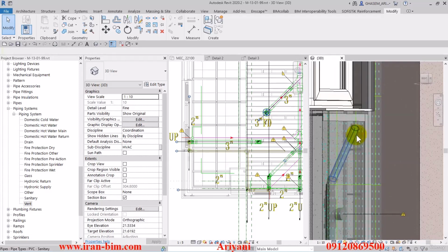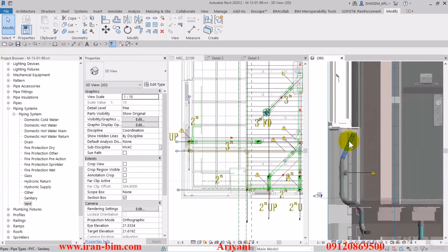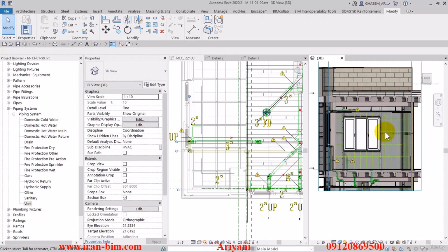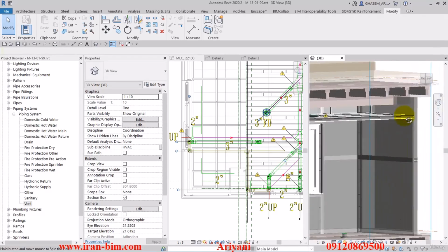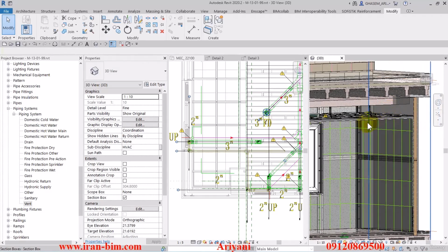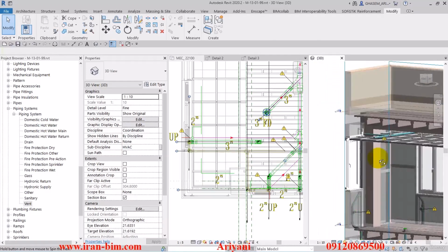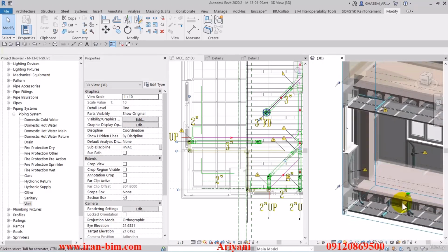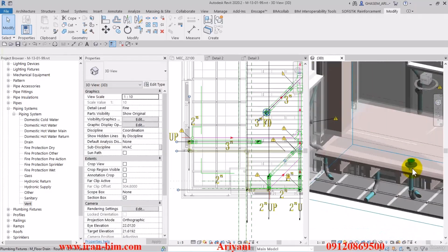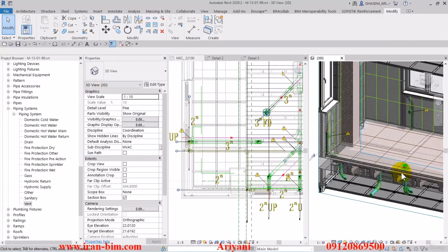Now, one of the advantages of using wall posts is when we're drawing the pipes in a plan such as this one, and there are clashes happening with the vents and the canals and the ducts that go through the walls. As an example, you can imagine that a canal has to go through here and it needs an opening. The wall posts help us to resolve these issues. For example, when we have a drain like here, we need to do core drillings as well.